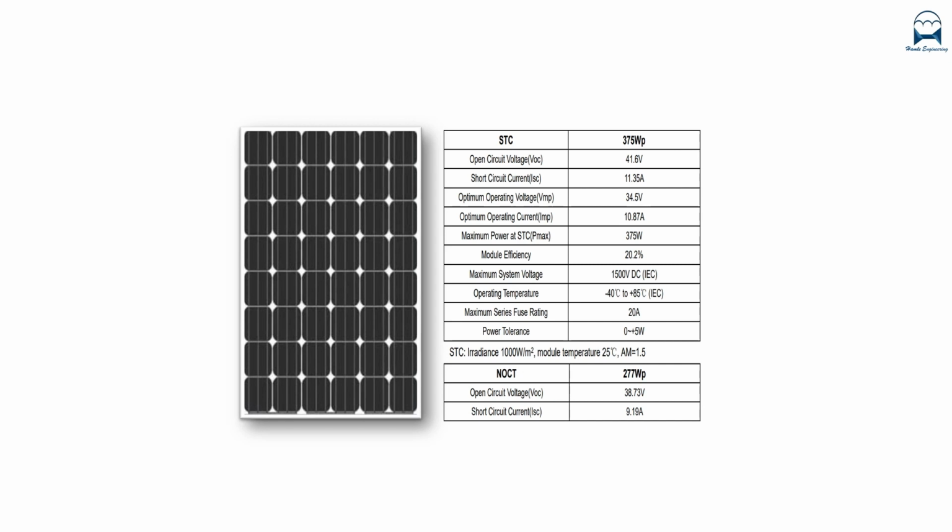This is generally referred to as a full sun condition, that is, full irradiance. Less than full sun will reduce the current output of the cell by a proportional amount. For example, if only 1/2 of the sun's energy, 500 watt per meter square, is available, the amount of output current is roughly cut in half because the solar cell only has half the brightness to generate electricity.